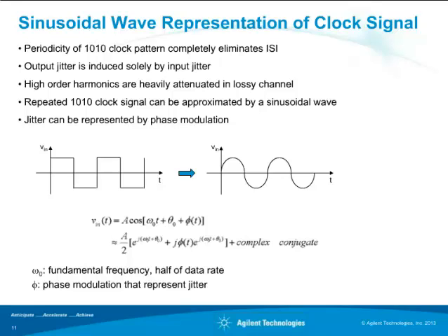Okay. Next question. This is kind of a long question from John Bay. In the case of HDMI or DDR, the clock signal is transmitted along with the data signal. That is, both clock and data suffer jitter amplification. This is a sort of synchronous clocking. When data is fetched by the clock, what will be the impact of jitter amplification? And can ADS simulate the statistical eye with reference to a non-ideal clock? I think the last part's answer is no, right? We assume an embedded clock in channel simulation so far.